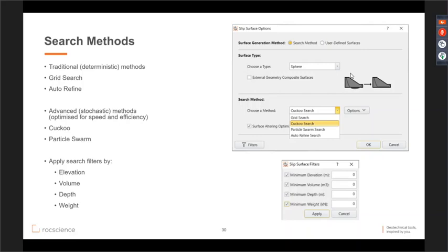So you can see here the different search methods. One of these up here is wedge, where you can specifically define 2 intersecting planes and a point of intersection. It will calculate the factor of safety of that specific wedge you've defined, or you can define 2 intersecting planes, and the software will float those planes through your slope and find the location where those planes intersect that has the lowest factor of safety, for user-defined dip and dip directions of release planes.